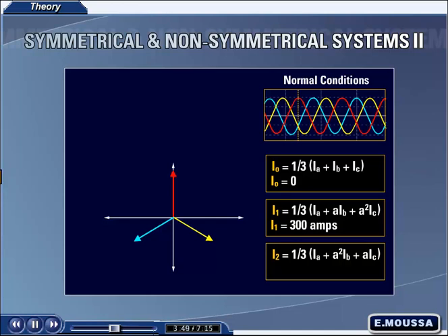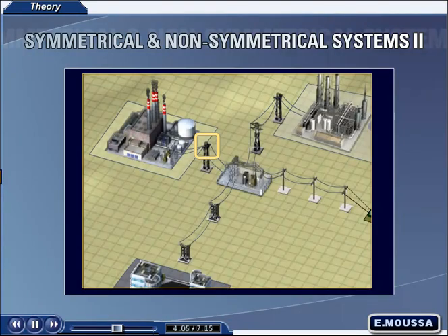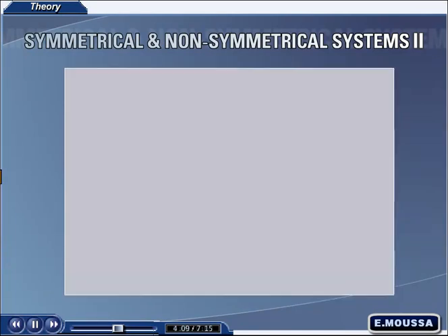Now that the 3 positions are determined, we can complete their addition. By adding phase B and C to A, we end up with a negative sequence of 0 amps. As predicted by Fortescue, only positive current exists. Now a fault occurs on phase A.